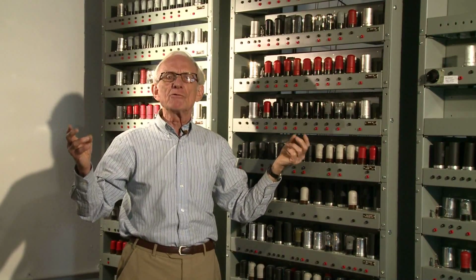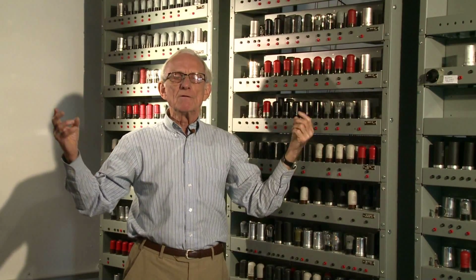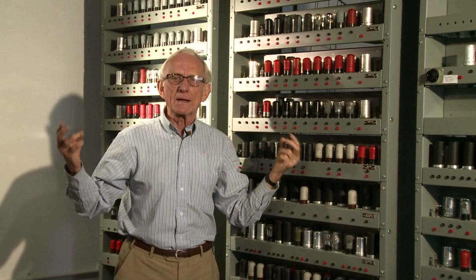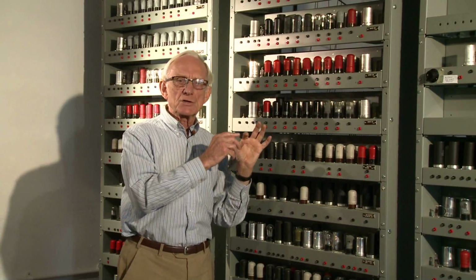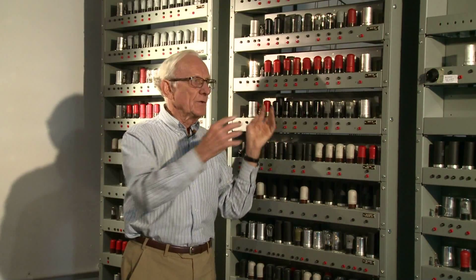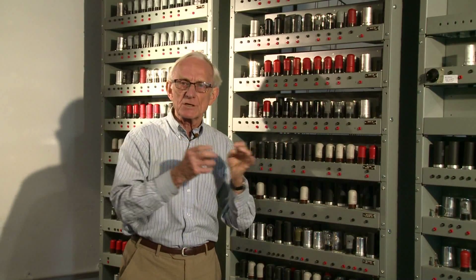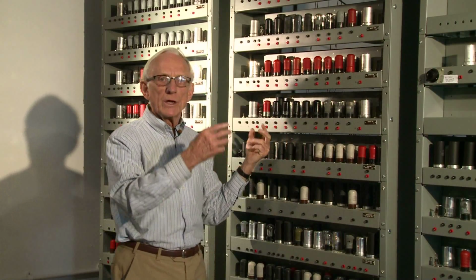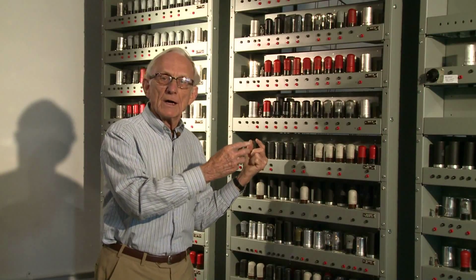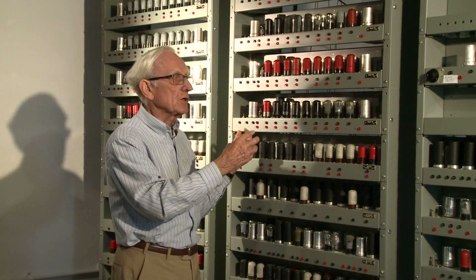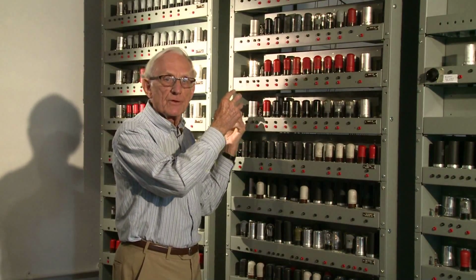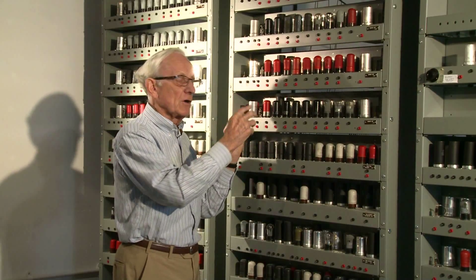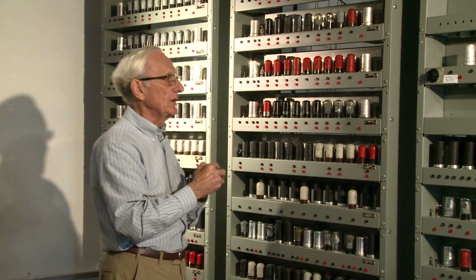We call them tanks. The original machine had mercury tanks, 5 feet long. We use that nomenclature. It's a tank which has got acoustic pulses. In the case of the main memory, 576 pulses running down the tank. We're going to use wire delay lines because they're safer than mercury, but while we're waiting for those to be finally completed, we've got little semiconductor units which we'll see later.